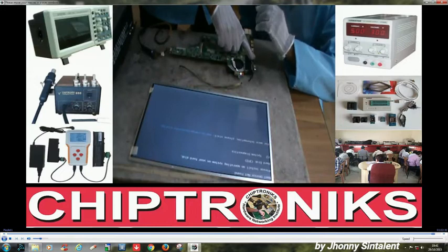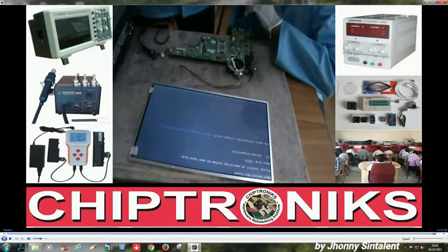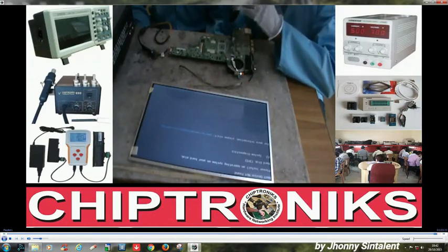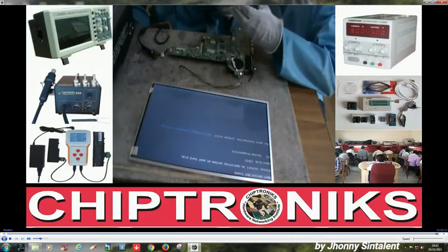So that means our BGA process has been completed without any failure, and the complete success of BGA depends, as I've already told you, on two things. First, using a correct BGA machine, and second, the manual process that we have used: board cleaning, making balls, no trace marks on the PCB. That is very important.